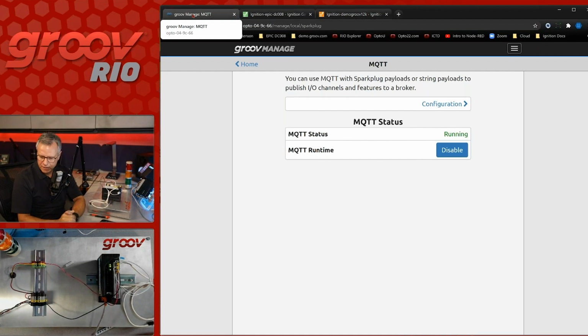Any closing thoughts there, Doug, from your end, from a Grantek system integrator perspective? No, I'm very much looking forward to using MQTT in the future. It's a great protocol. I think we're going to see it start really taking over for some of those applications, especially remote IO, where you have to build a panel, put in a remote rack, get power out there, and run some communications protocol. Now we can get PoE out there and get that data back in very quickly, very easily, and very securely.